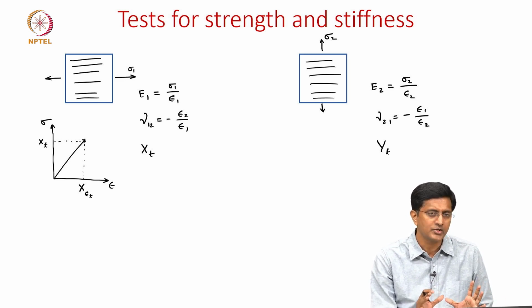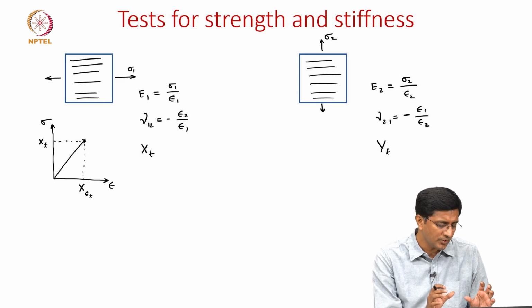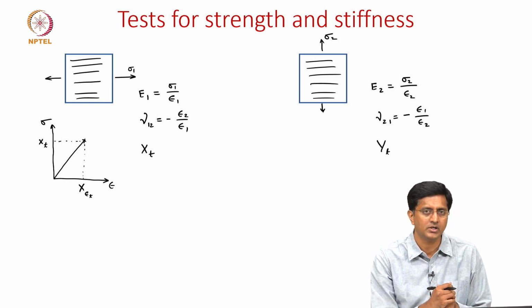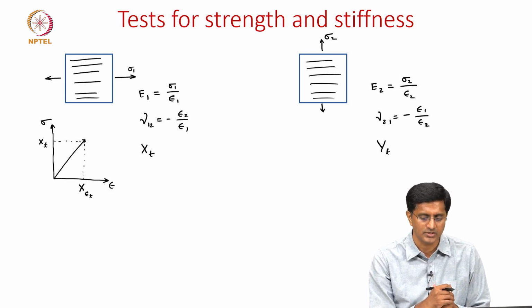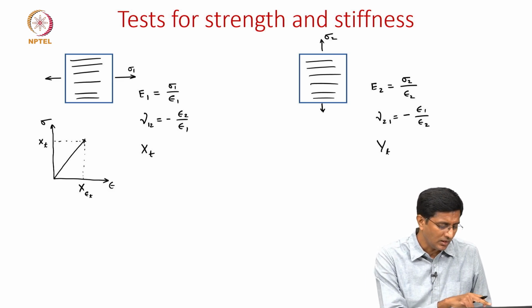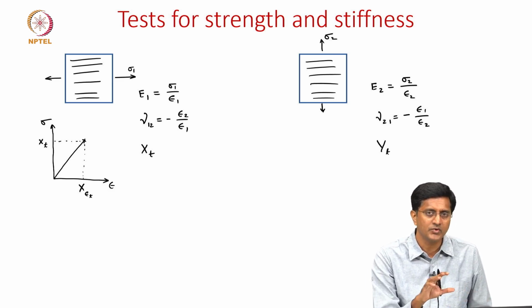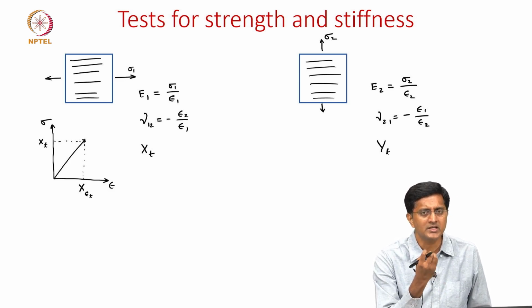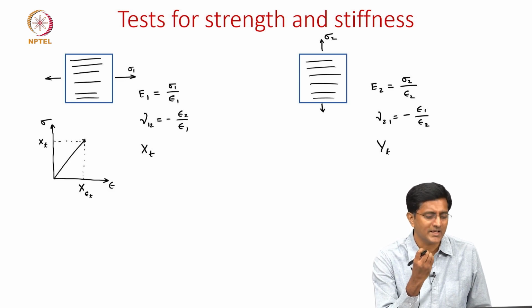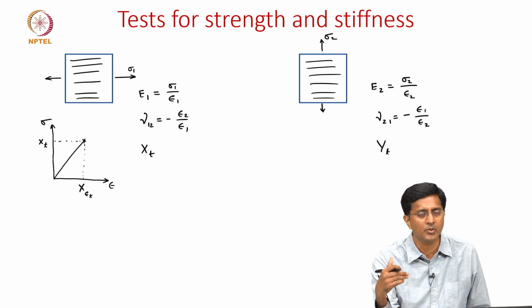So what we are trying to show is these simple experiments will give you some of the elastic constants and the strengths, as well as the strains corresponding to those strengths. But neither of these two experiments will give you any shear properties. So for that we need to apply a shear load, but in practice applying shear load is not as simple as applying the normal loads.